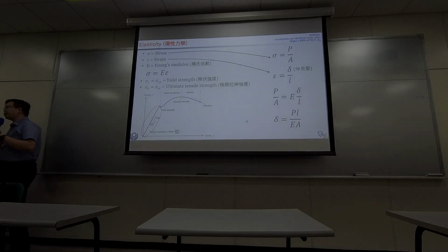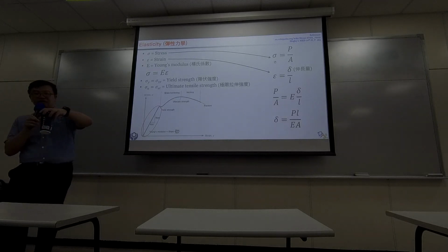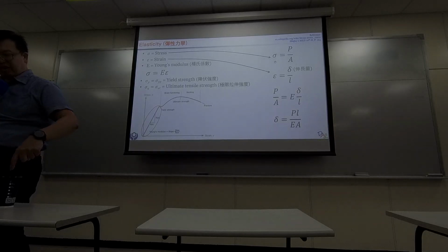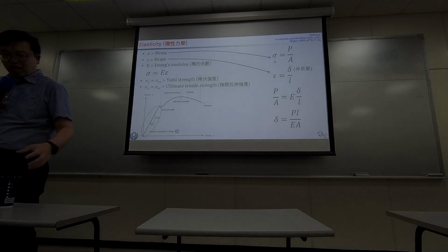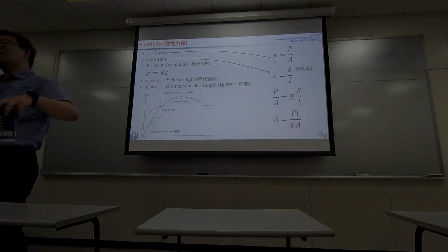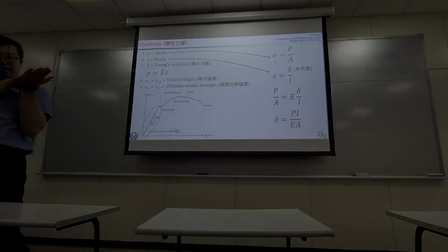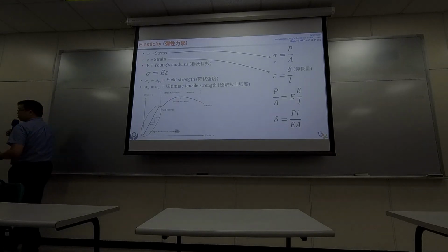Okay, so let's review some of the equations. By definition, stress equals the force over the effective area. If it's a normal stress, basically if I apply some kind of compression, I divide how much force I apply by the circular area, the effective area that carries my force, and then I know the stress accumulated inside this cylinder. If I do shearing, for example, I am shearing like this, with the pulling force and the effective area, then I know the shearing stress.